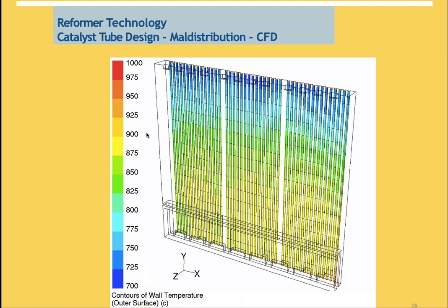Okay, here on the tube, the low steam to carbon ratio can lead to this criteria: low operating temperature and high carbon content, C2 plus, which is heavier, and sulfur slip killing the active nickel sites. Okay, you have to remark this. And poor feed mixing between steam and the natural gas at the steam mix point.